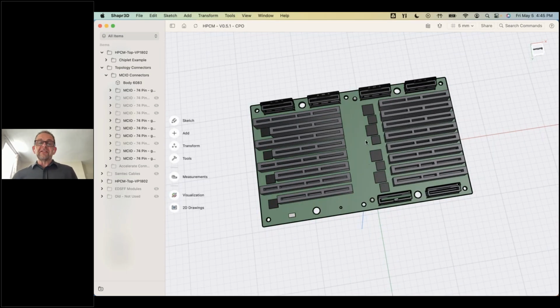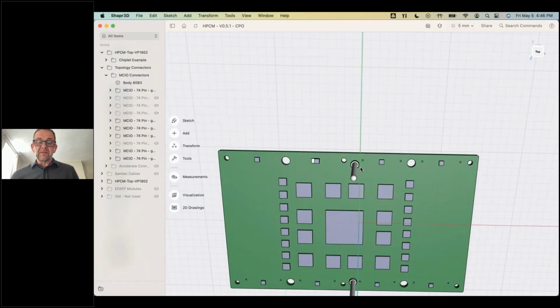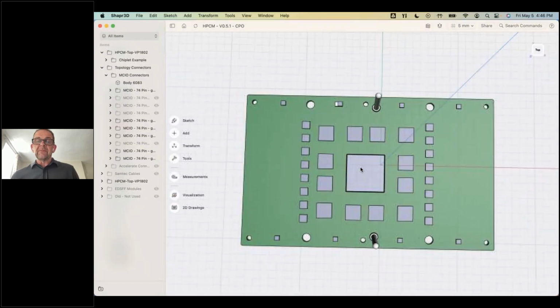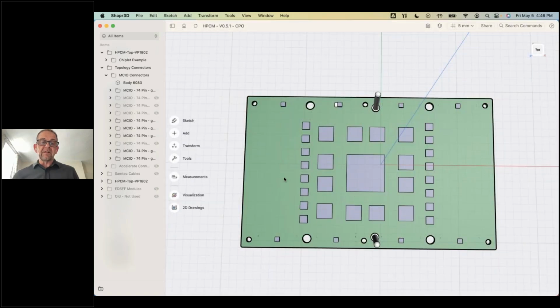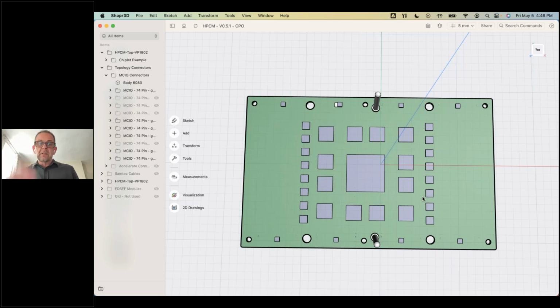So no, sorry. These are sideband management chips, which I'm working with Lattice on. So that would be more of the fabric management. But no, the power, sorry, I've not shown the power. I showed it in the PowerPoint, but it would be in these regions here, like it is on a traditional OEM. Or you could potentially put power between the devices if it made sense to. So the point of load power is not shown here.